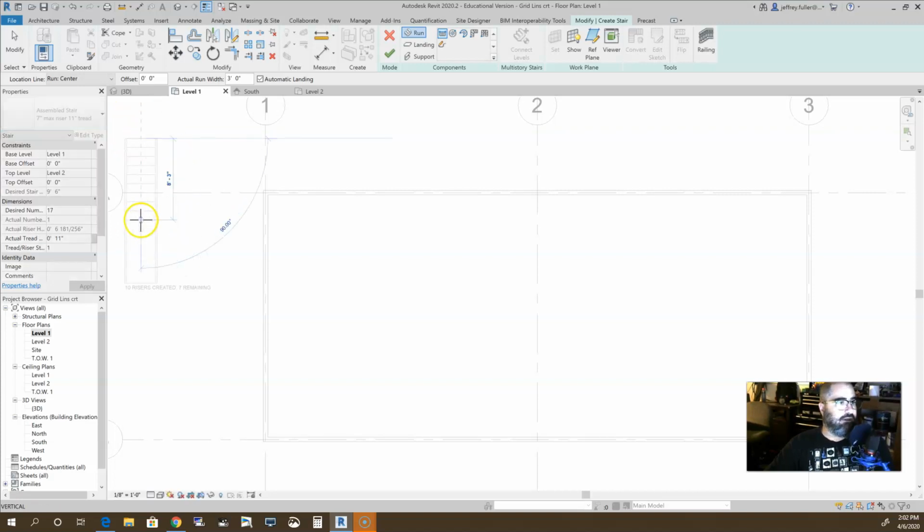Okay. And I didn't want to start that just yet. And let's see, it also has the different sizes for your risers and treads. I'm not sure, tread riser 1. But anyway, the actual tread is 11 inches. The riser, it doesn't make it where we can adjust it, but we can adjust it much later. Not that you'd really have to. Revit is programmed to set the risers and treads according to code and most allowable areas.